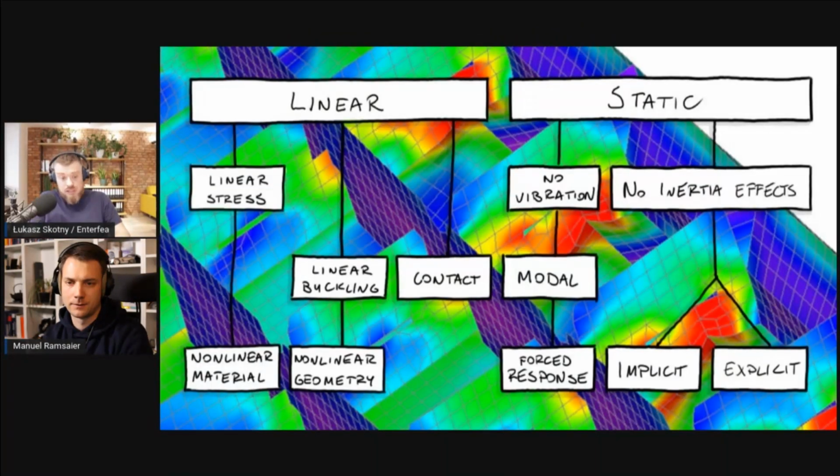And honestly, nobody is willing to make the effort to do this. It's way more effective to actually do nonlinear FEA and simply do it correctly for every application, rather than writing huge, thick books of, if you're solving this or that, the multiplier should be this much, because that would be such an insane amount of work that it's beyond crazy. I think there's also a bit of history here, because we were not always able to do nonlinear analysis, and in those times you had no other measure than to make assumptions from your linear calculations.